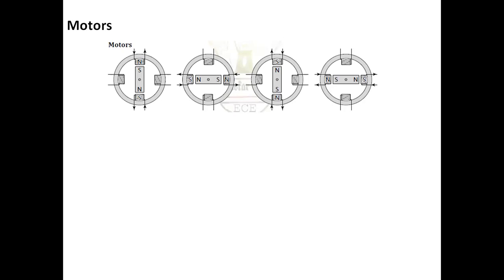The motor consists of a permanent magnet rotor mounted on the shaft. Surrounding the rotor is a stator, where we have a number of coils that can be energized so as to form electromagnetic poles. Like in the figure, you can see that the coils are energized in a sequence, so the rotor is attracted to successive angular positions, stepping around through one rotation.